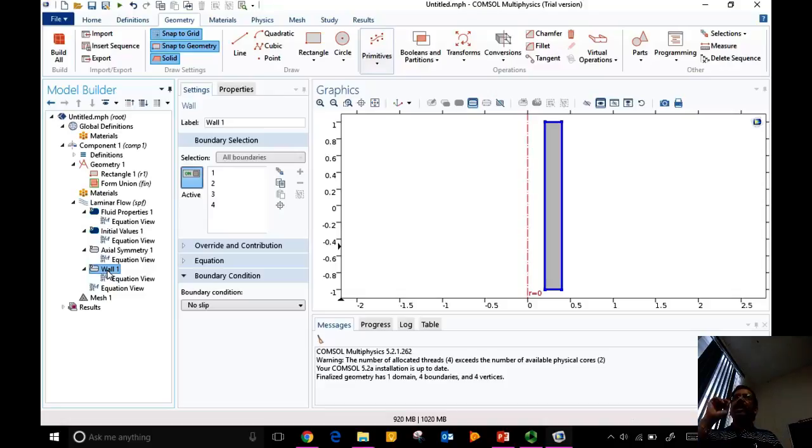Okay? But if you have, for example, heating from one boundary, can you create a flow inside? Answer is yes, because if you're heating from one boundary and cooling from the other boundary, the density near the hot wall is going to go down, and so gravity will then start raising it up if you put g in the vertical direction. Okay, so you can set up a density gradient in a gravitational field and drive that. In that case, the driving comes from the rho g term, or typically the driving comes from the boundary condition, right? So in this case, I'm going to pick the top boundary.